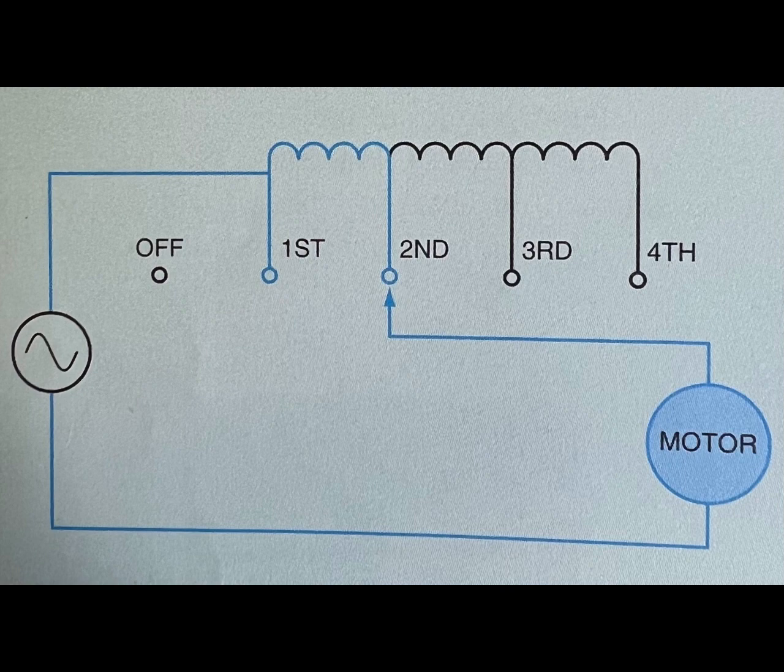Since only positive voltage pulses are being conducted, the voltage applied to the load is DC. A DC voltage applied to a resistive load, such as an incandescent lamp, will not cause any harm, but a great deal of harm can be done if a DC voltage is applied to an inductive load, such as the stator winding of a motor.